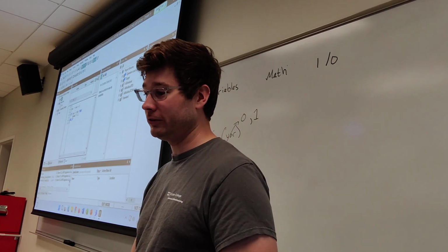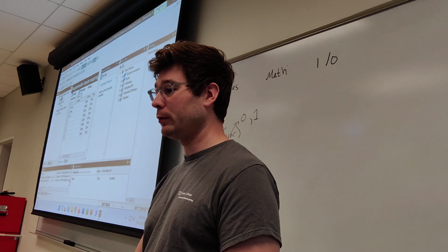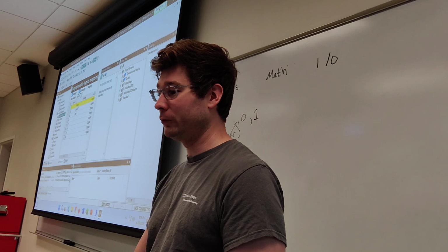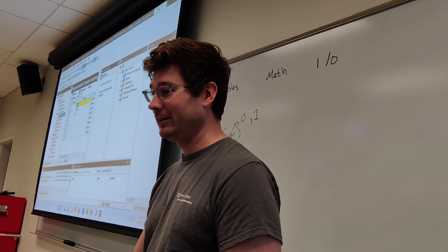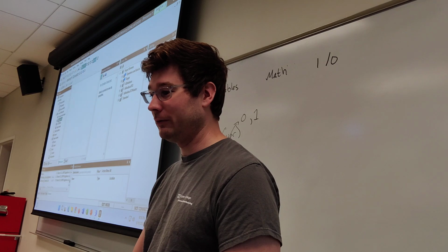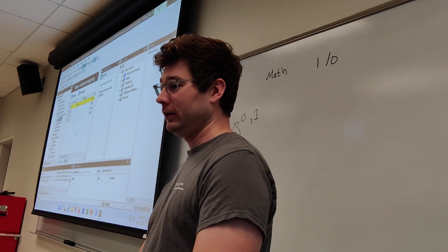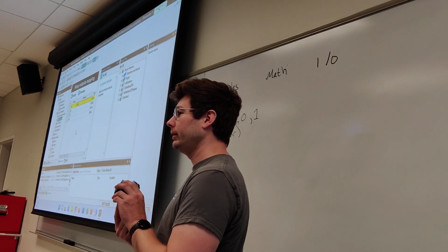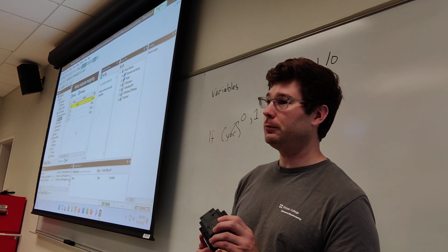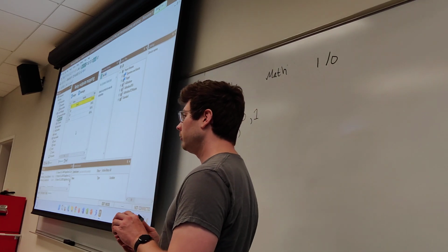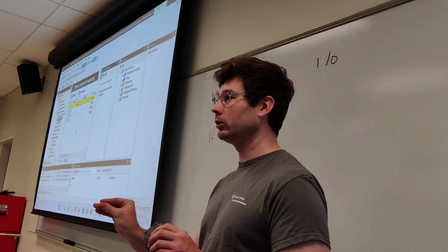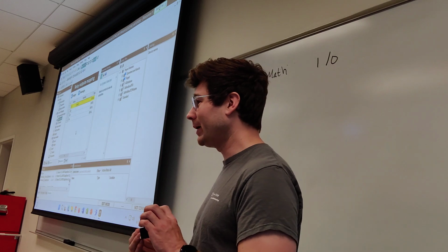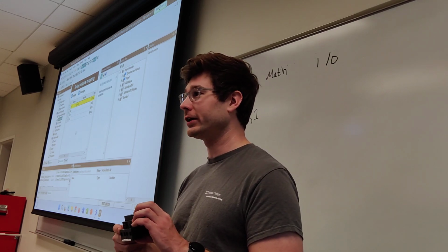Okay, I actually made a mistake just there, sorry, not to confuse you guys. This is in the programmable inputs. But if I wanted to control a relay, which is what I was actually showing, I'm going to move my bread variable and attach it to a relay. Sorry if that's confused you, but we jumped down to our relays on the bottom here. Now we're assigning variables to our relays. If we set these variables to 1 or 0, we're triggering our relays to turn them on or off, to make them open or closed. To attach one of these terminals to nothing, or to attach it to a power supply that'll theoretically turn it on at whatever voltage is on our other terminal.